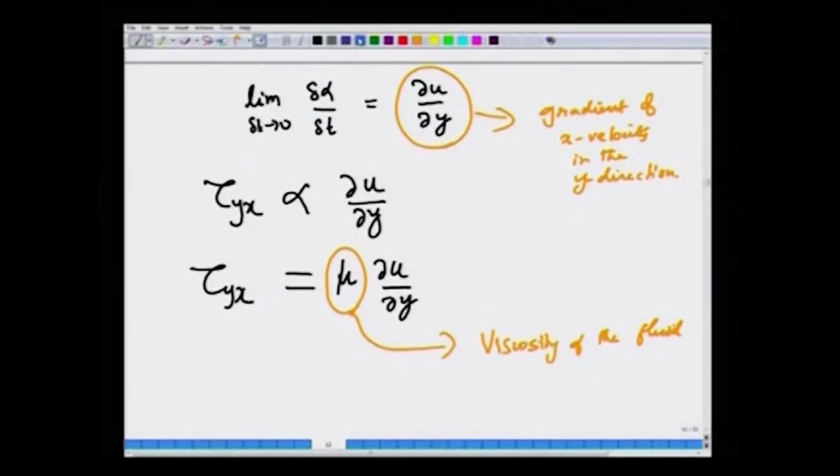That is what we mean when we say a fluid cannot resist any amount of shear stress, because it continues to deform and therefore, it flows. So, the viscosity tells you about the resistance to flow in a fluid, just as the elastic modulus of a solid tells you how difficult it is to deform a given solid. So, this simple equation is called Newton's law of viscosity.